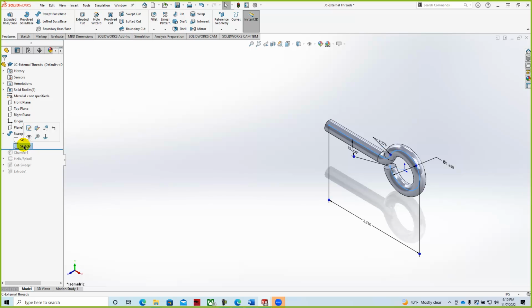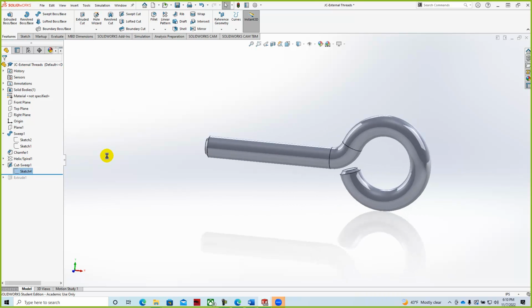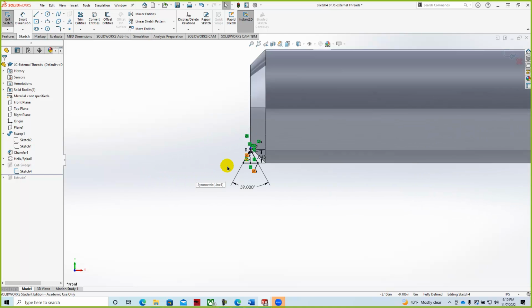And we have two pieces. We have the sketch right here, and then the part that we are going to sweep around that sketch. We sweep it, chamfer the end of it, place a helix, and then use that same technique of creating a sketch for that sweep cut.